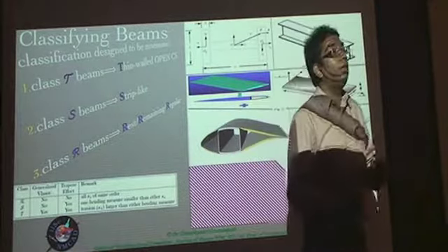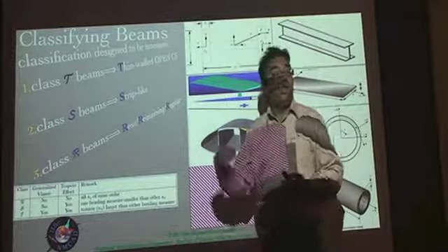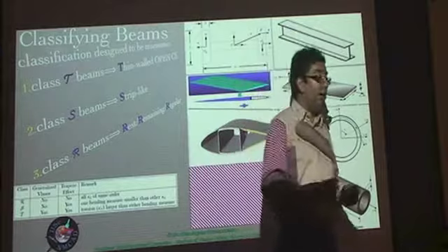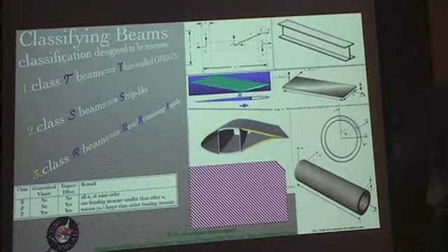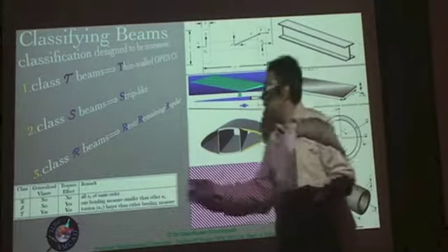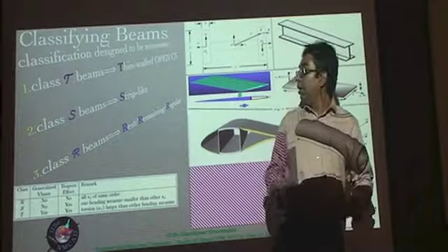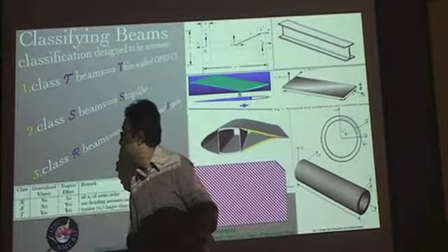One bending curvature is not much larger or much smaller compared to the other bending curvature, whereas the torsional curvature can be fairly large if it's subjected to torque, which can go all the way up to the failure of the material. So you can have very large kappa 1s there, and therefore the effect will be pronounced, and so it becomes a fairly complex situation that you have there.